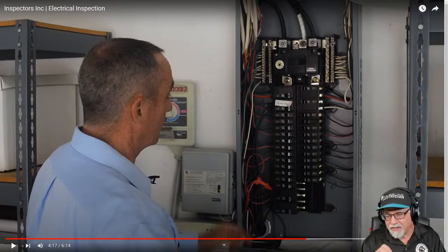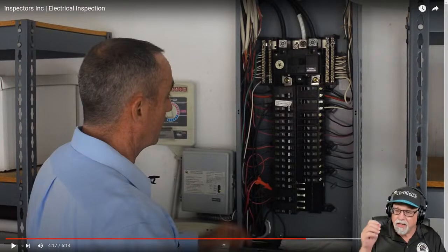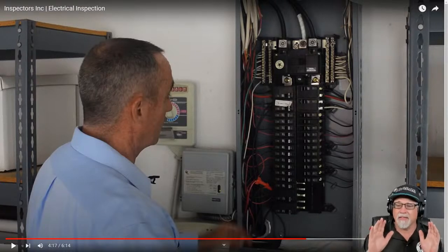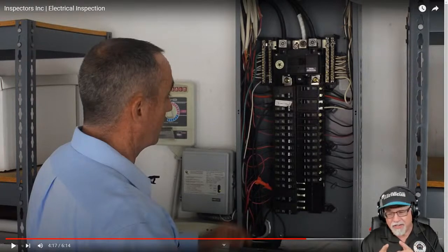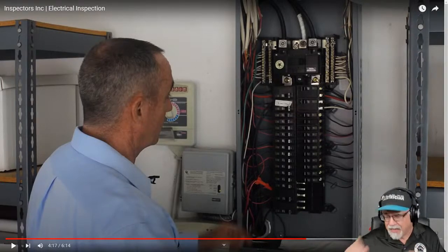The reason I bring this up is because if you go blindly in there and say, okay, 14's going to 15, 10 goes on to 30, 12's going to 20, yeah, for general applications, that's absolutely correct. But there are allowances, and you have to be very aware of that before you call it out, whether it's to something like a motor, or an outdoor air conditioning unit or air handling unit or something like that. And where do we get that? I just want to show you.